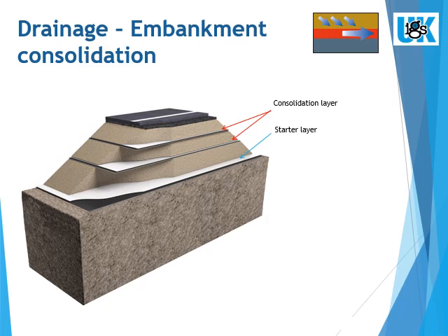By putting intermediate layers of geocomposite drain into the embankment, this will accelerate the process considerably. Intermediate stone drainage blankets are rarely used as they are so impractical. Again, a case study will help us to explain.